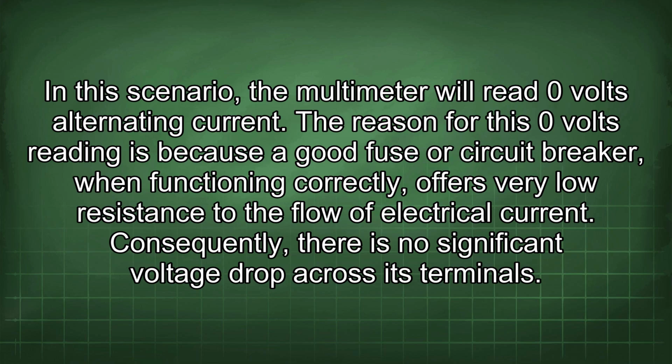The reason for this 0 volts reading is because a good fuse or circuit breaker, when functioning correctly, offers very low resistance to the flow of electrical current. Consequently, there is no significant voltage drop across its terminals.